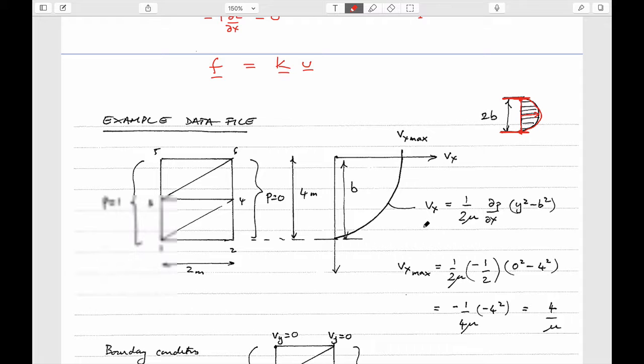And the solution for that is this. The velocity in the x direction is conditioned by the viscosity and the pressure gradient between the upstream and downstream, dp dx as you go downstream. So you can imagine this being a conduit which is upstream or downstream. If you looked at the velocity profile upstream, it would be identical to this.